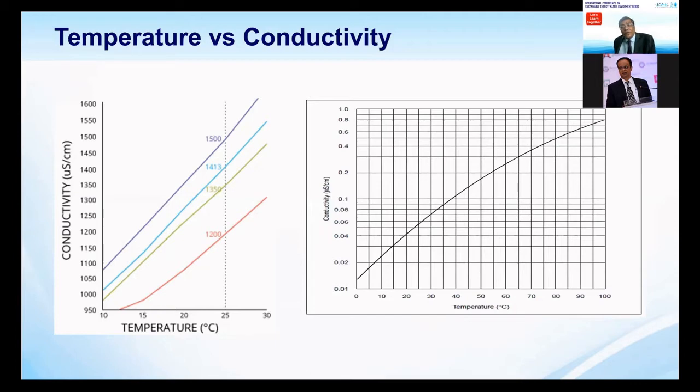It is better always to measure the online or flowing water pH at the duty point. You can keep the water flowing in a beaker and put the electrode in that, and then you will have a representative pH of your stream.